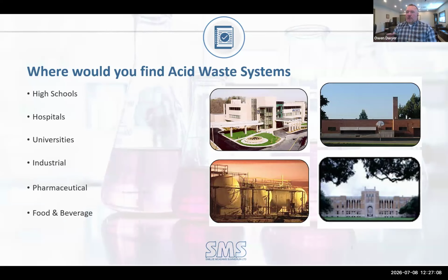In the event during charging that there's a battery failure, that's sulfuric acid spilling onto the floor, and there's going to be floor drains or a trench drain in and around that area for that exact reason, or wash down. You're not tying that into your sanitary directly without going through a neutralization system first. So that's a good example for industrial applications or for chemical storage closets.